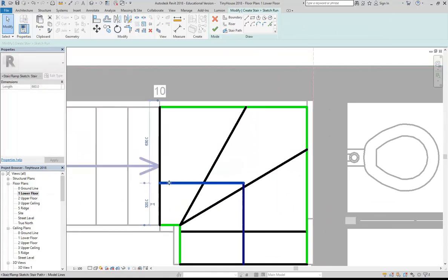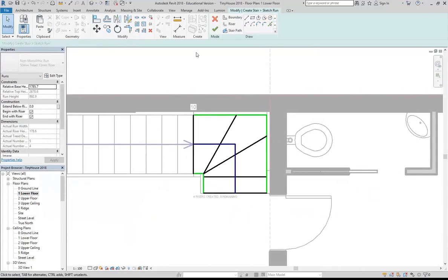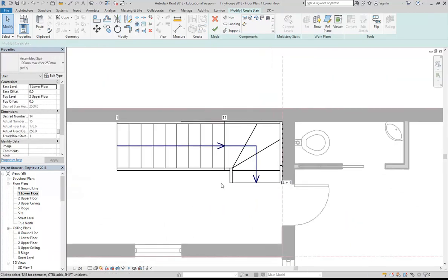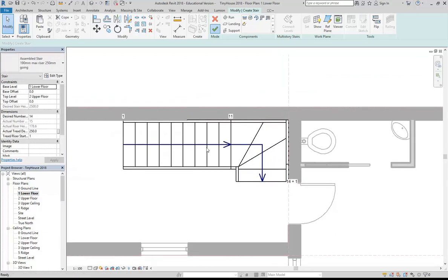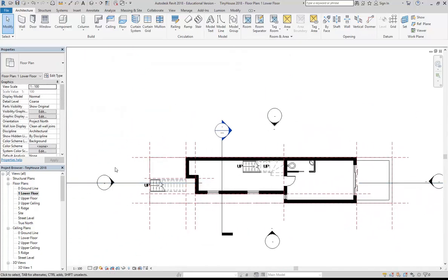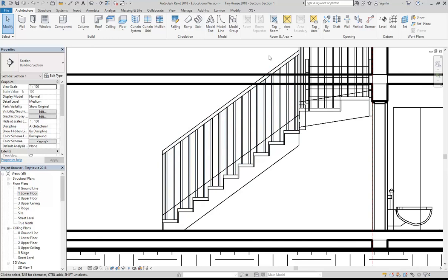But stairs are a complicated thing. And if you ever talk to someone who's had to build a stair, they can tell you about all the little things that aren't so obvious when you go to design them. Okay, so I've got the basic shape for my stairs, and then I need to make a hole in the floor. And so to work it out properly, you can have a look in your section view, and then you can see, just using the ruler, what the height is from your, well, starting with the first step there, from this first step up to the, well, at the moment it's a floor, but we'll say that's the ceiling above, is, what, 2100?